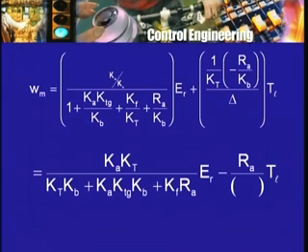So for ER now, substitute K tacho generator into omega d. In the numerator I will have Ka Kt into Ktg into omega d, and in the denominator I will have this sum. Now can you see why omega m will turn out to be less than omega d? That is because what multiplies omega d in the numerator is Ka Kt into K tacho generator.